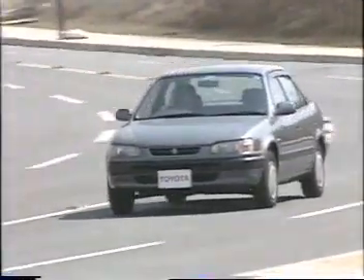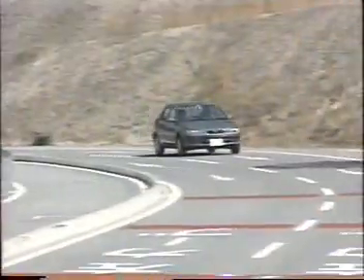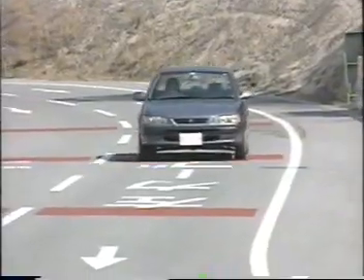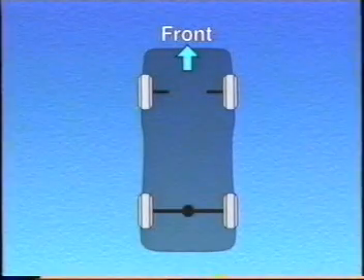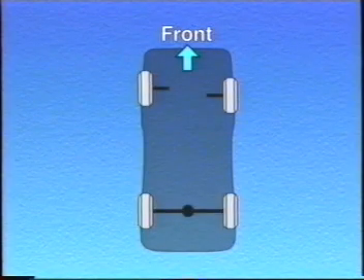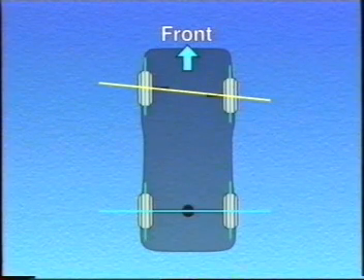Usually, the term wheel alignment is used to refer mainly to the alignment of the front wheels. However, total four-wheel alignment, including rear wheel alignment, has become important because of the recent increasing demand for more sophisticated driving performance. For example, even if the alignment for each of the four wheels is normal, straight-ahead stability will be reduced when the front and rear axles are not parallel.